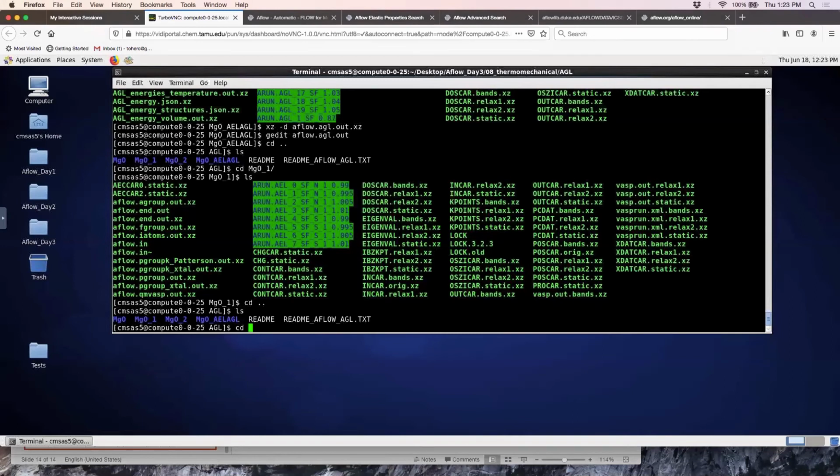So somebody's asking, is there an advantage to switching off the symmetry? So the main thing you might want to do it for is if you want to check the robustness of the calculation. So you have some redundancy in the calculation. You're basically doing the same calculation in a couple of different directions. And so then you can check that the values that are supposed to be equal to each other are still equal to each other. So you can really check how robust your calculation is.